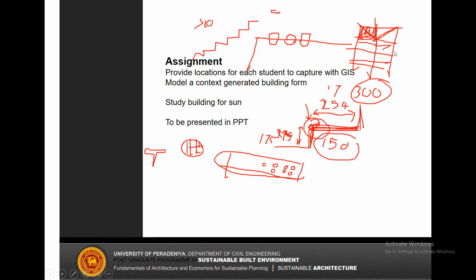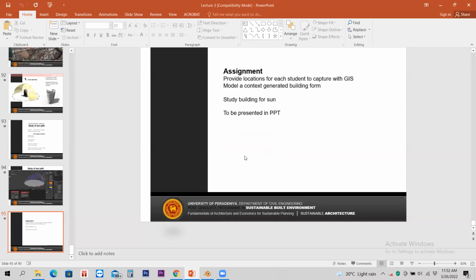And railing also is something important. The railing height in a staircase, 1.2 meter height is required. Usually a balcony rail is 900, so most people use 900 high railing. So that is also causing injuries. Okay. Right. Thank you so much, sir. Okay.